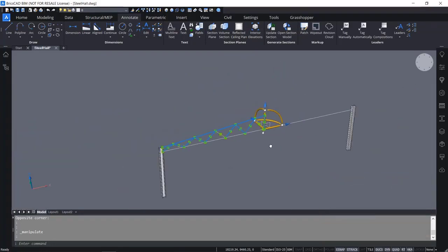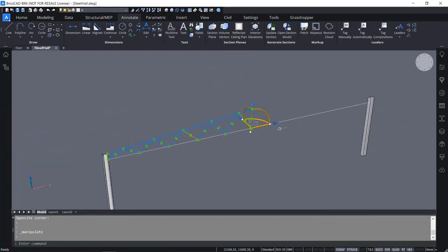And then we want to mirror. How do you do that? You have these blue arrows, and these are the ones that you need for mirroring. So I select the one in the X direction. And then you see I'm mirroring this entity. If I don't do anything, it will just mirror it and it won't make a copy or anything.